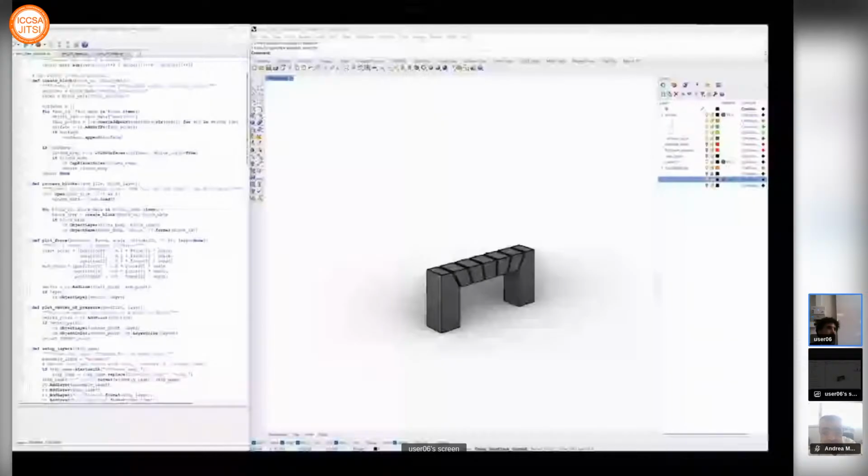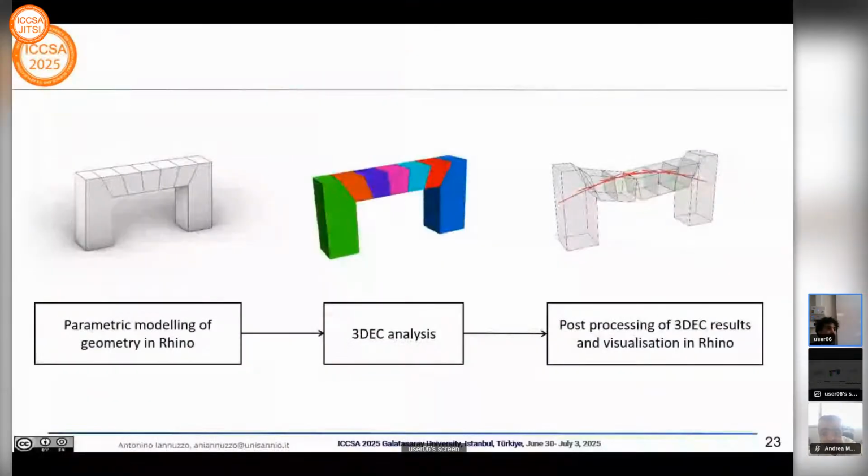This one is the geometry rebuilt with internal forces from 3DEC. They are, if you look, very close to the thrust lines as they should be. These are the resultants calculated from 3DEC, where you get back the sub-contact forces. Then you have to repeat the resultant over the interface. It looks like limit analysis, but it's not limit analysis, it's 3D. But in the case of the bridge, we didn't find any.